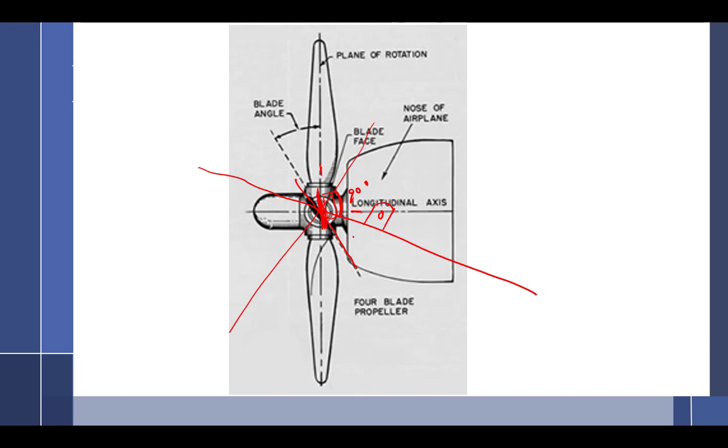It's not a problem. And the trick to it is when you put the protractor on something and you zero it out sitting this way, and you put it up to the blade sitting this way, you're going to walk around the airplane and you're going to want to put it back on the blade this way, but you just messed it all up. Once you set up your protractor to read this way, and you put it on the blade right here, then when you walk around to the other side of the blade, you have to continue to hold it the same way.